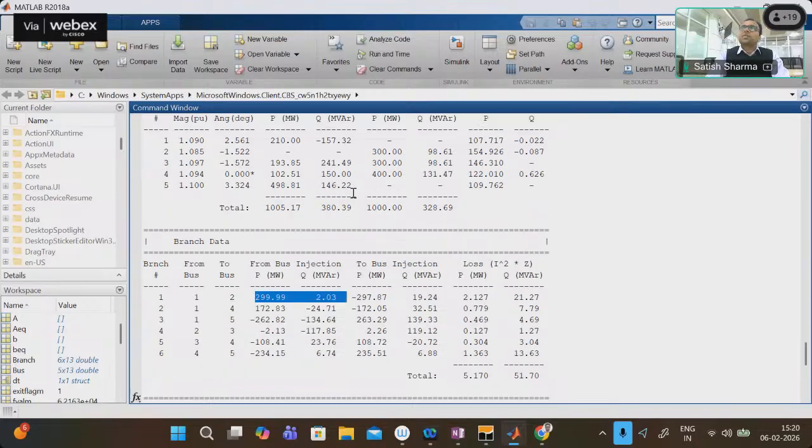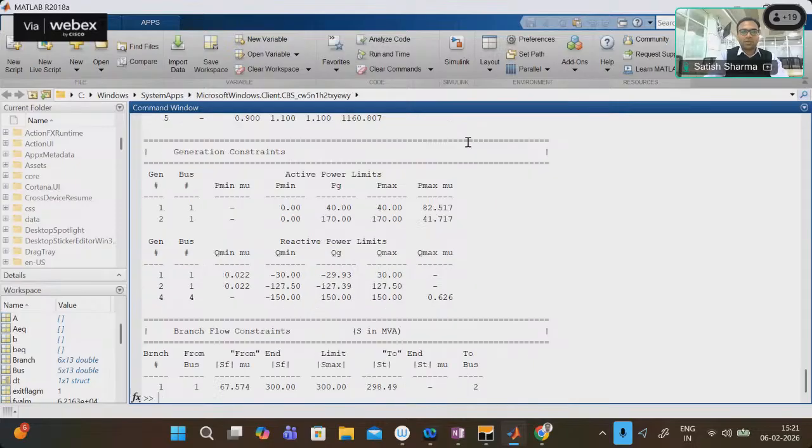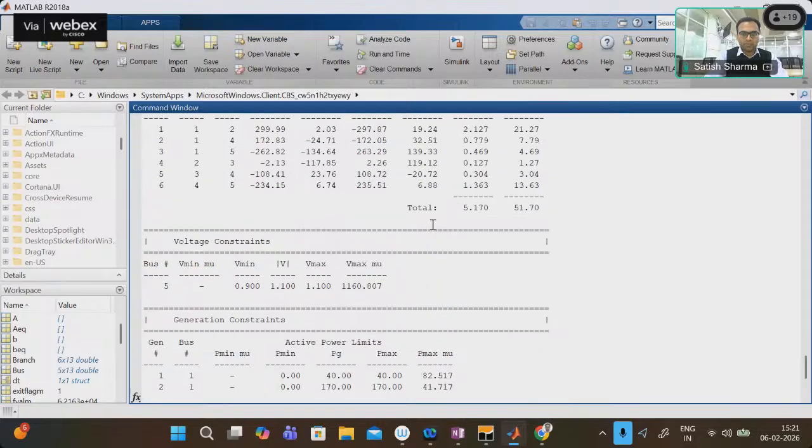If you restrict certain lines, if line flows are being restricted, then the output will change, the incremental cost of the generators will change, two areas will be created along with that particular line, and you can see that the different LMPs, basically lambdas, are available here. So these are like nodal prices, and by looking at this you can, okay, wait.